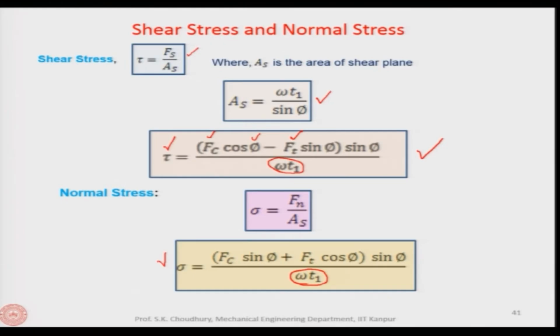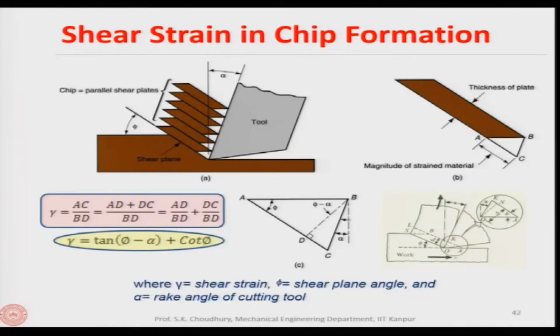D is the diameter of the workpiece. So, if you know that you have to machine a workpiece of a certain diameter and with a certain revolution RPM, then you will know what power it will be consuming if we can find out analytically the value of Fc, which is the cutting force. Okay, this is clear.